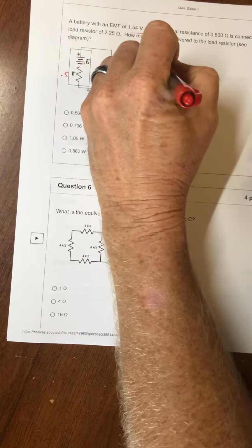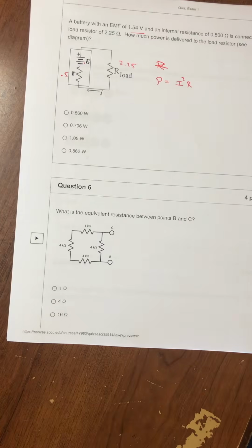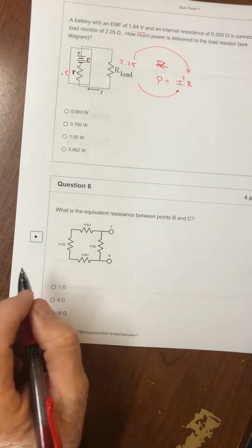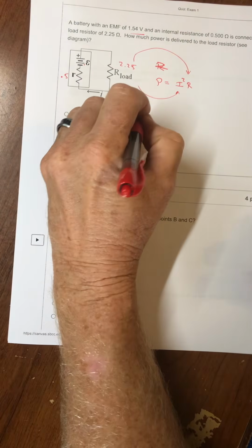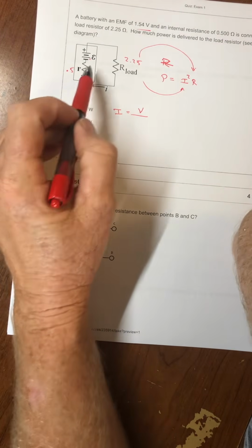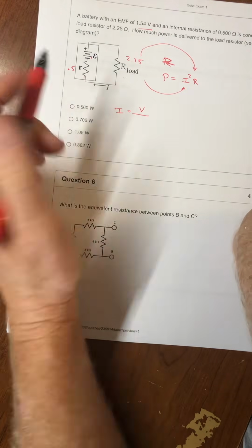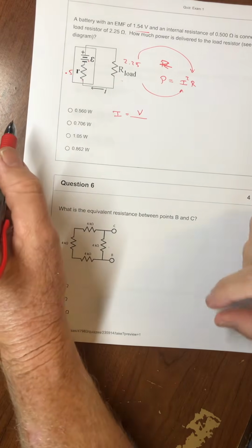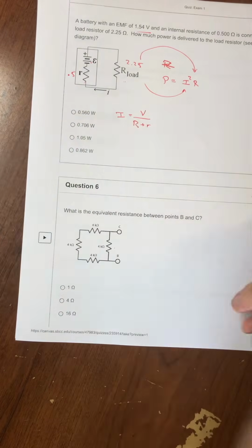All right, so there's a couple ways to do power. Maybe I'll focus my attention on I squared R. I need to put in the resistance of the load, but I also need the current. Well, the current's pretty easy to do because the load is in series with the internal resistance of the battery, because that's the way the battery works. It just has some resistance. So you have these two in series, and that's the equivalent of the load plus the internal one.